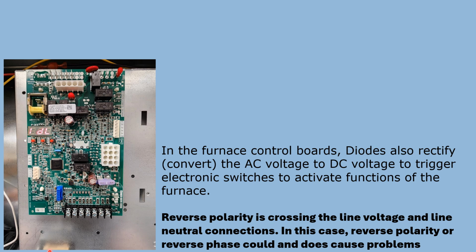Reverse polarity is crossing the line voltage and the line neutral connections. In this case, reverse polarity or reverse phase could and does cause problems when you're trying to feed power the wrong way through a one-way switch.